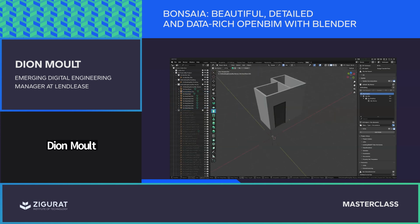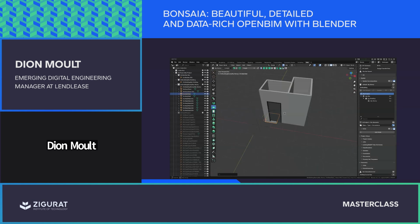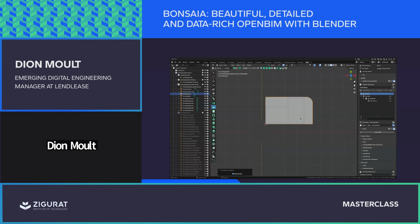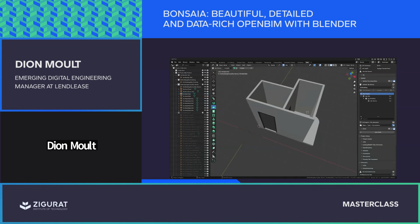Fantastic. Now let's draw in a floor slab. There's our slab. Go down to a top view. We'll fillet that. This is actually a question I get a lot. Many people think that because Blender is a mesh-based software, we're only dealing with meshes. That's not quite true. IFC has quite a large range of geometry types available. What we're doing here is actually precision modeling with solid extrusions. In this case, it's currently using the Open Cascade kernel, for those of you who are interested in that.